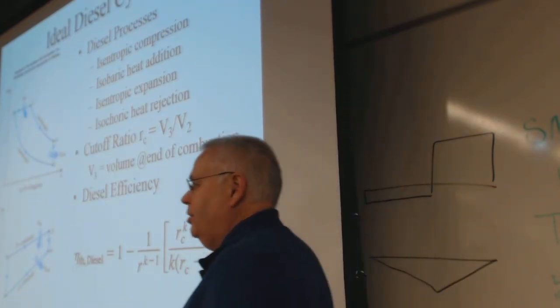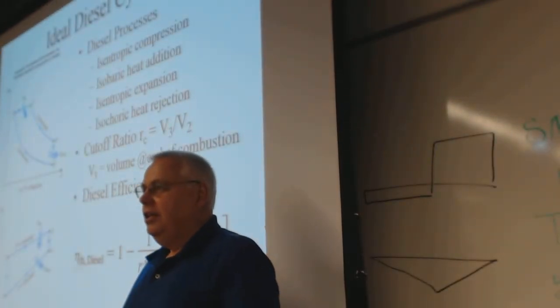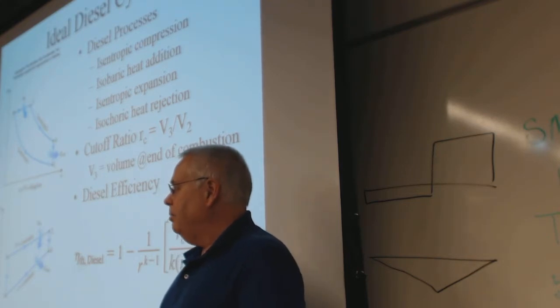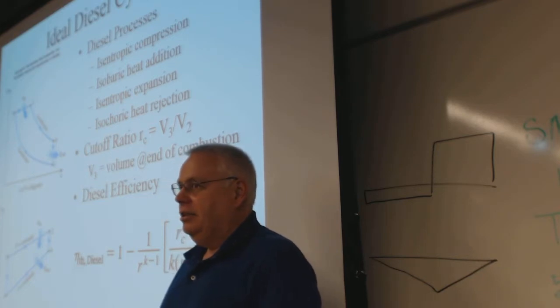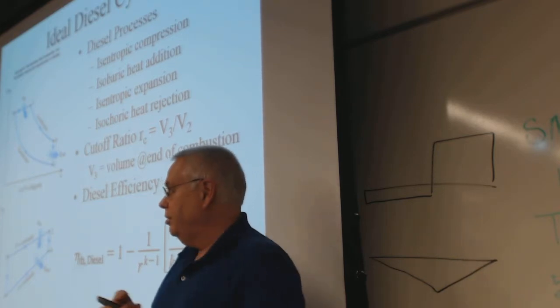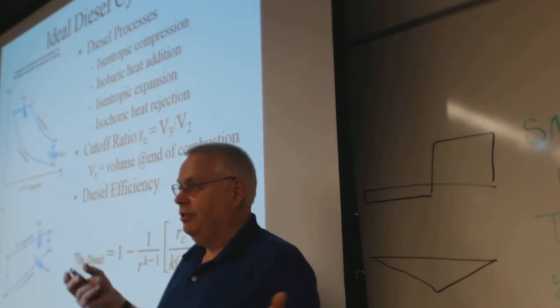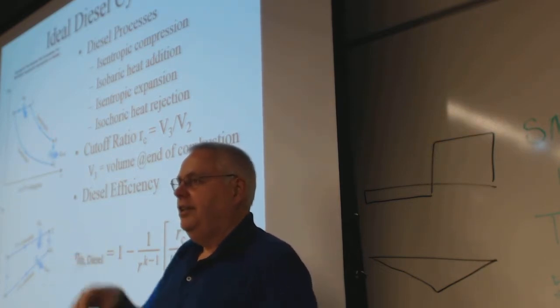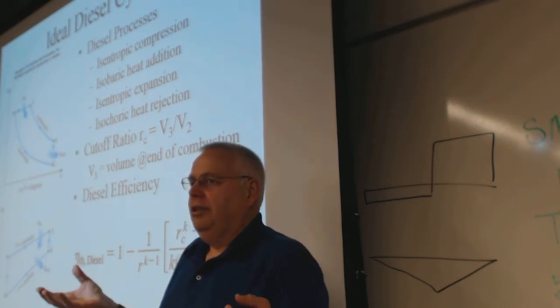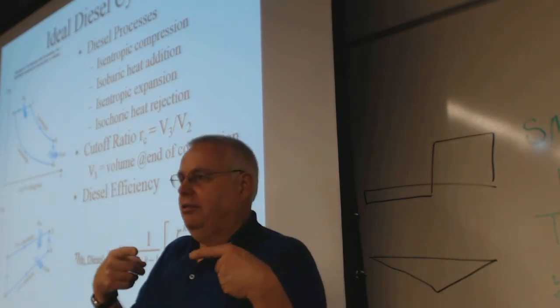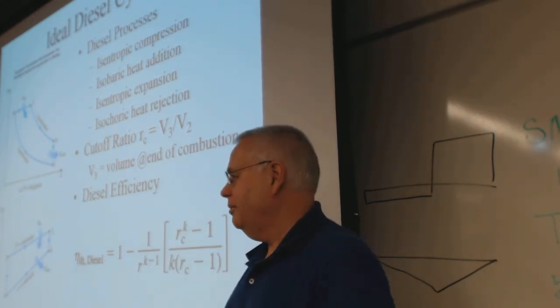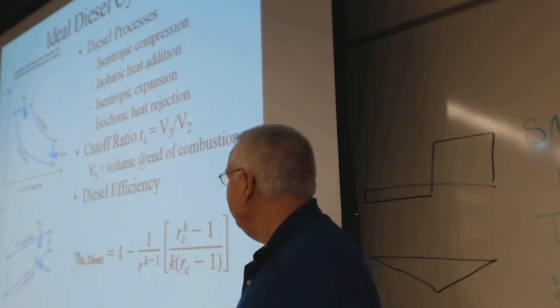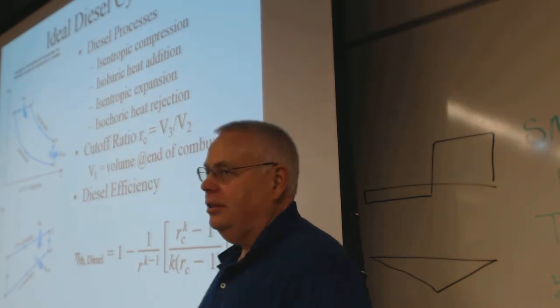A gas turbine has to turn a compressor, and it turns out the work ratio on the compressor for a jet fighter type engine is like 100% of the turbine work going into turning the compressor. There's no efficiency there because it's not turning a shaft, it's getting a thrust. So your work in could be 100% of the work out. You've got nothing to show for it, except a supersonic fighter jet. But anyway.